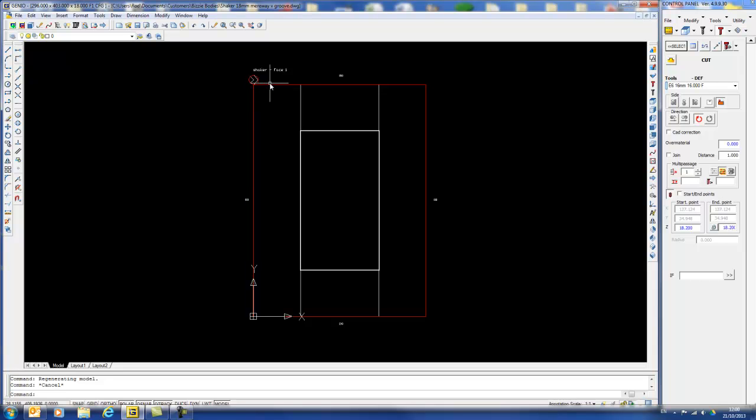One thing to make sure of whenever you're using the cut or the vertical mill, is that this red icon down here which says join to geometry, make sure it is red, so then as the geometry changes the machining will go with it. If it's green it won't link with it. Okay, the other two, now let's take these two lines up here, these are going to be vertical mill. So we're going to vertical mill.